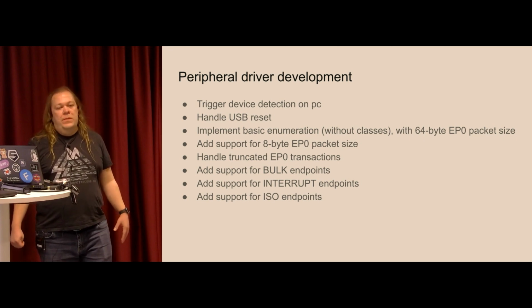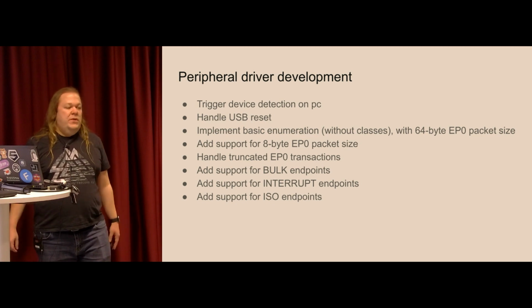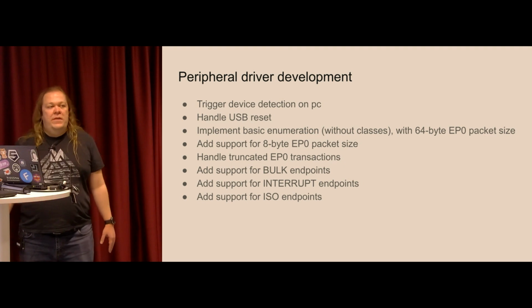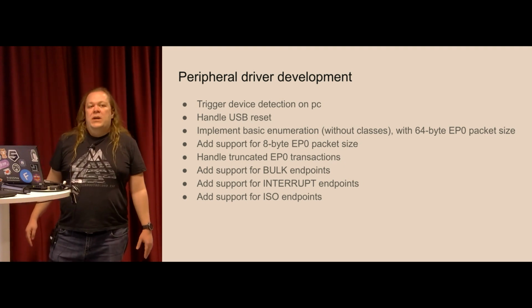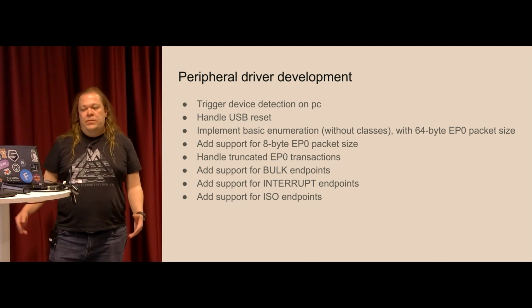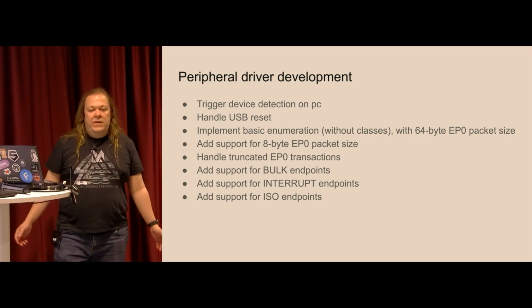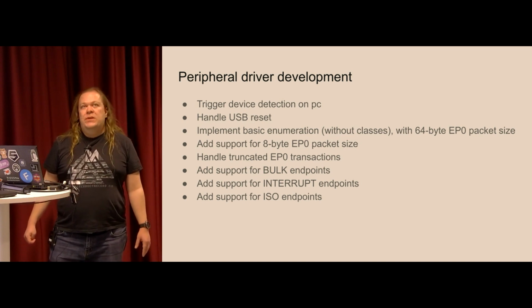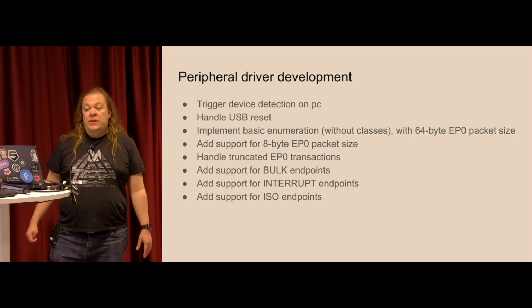This endpoint should provide some information. Usually all the information you need at this point is already provided by the usb-device crate, but it should be somehow transferred to the endpoint on the lower layer, because usb-device doesn't know anything about hardware. And here an interesting thing to do is to try enumeration without any classes.